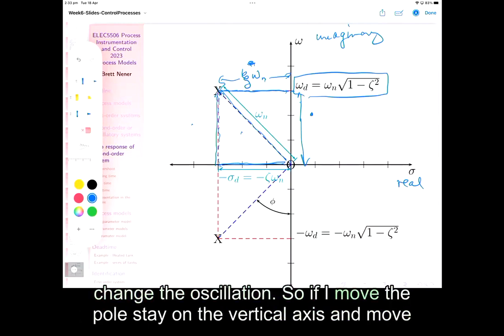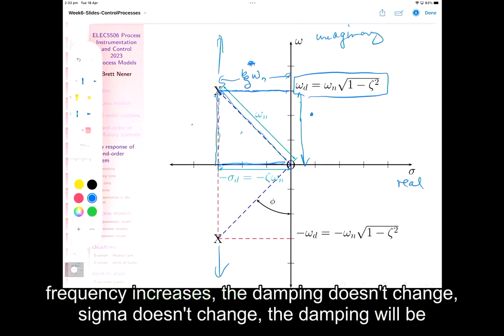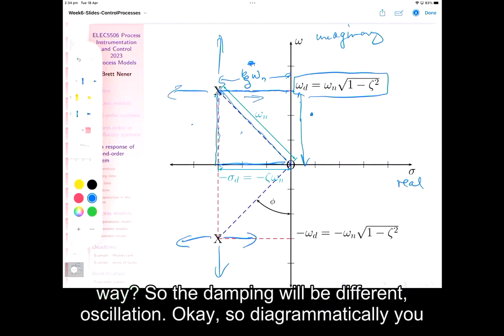So if I stay on the vertical axis and move the poles upwards like this, or downwards down here, what happens? The oscillation frequency increases. The damping doesn't change. Sigma doesn't change. Okay, so what if I this time go this way or this way, or this way, this way? What happens?